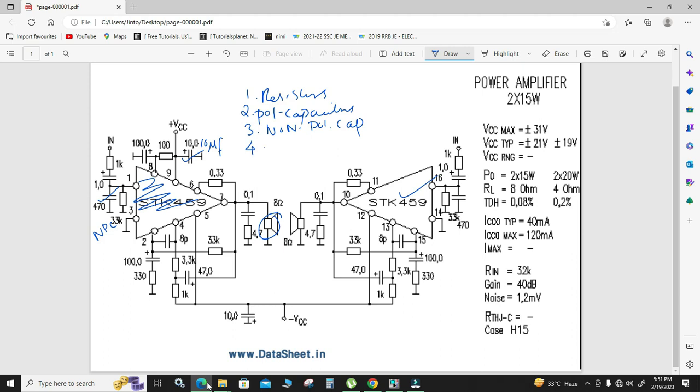Okay, then it is a speaker. In the speaker, and also the VCC and ground, each is connected using connectors. For example, the speaker has two pins, plus and minus. All these are connected to the connector. It's a two-pole connector, and the pitch is 2.54, which we are going to use.